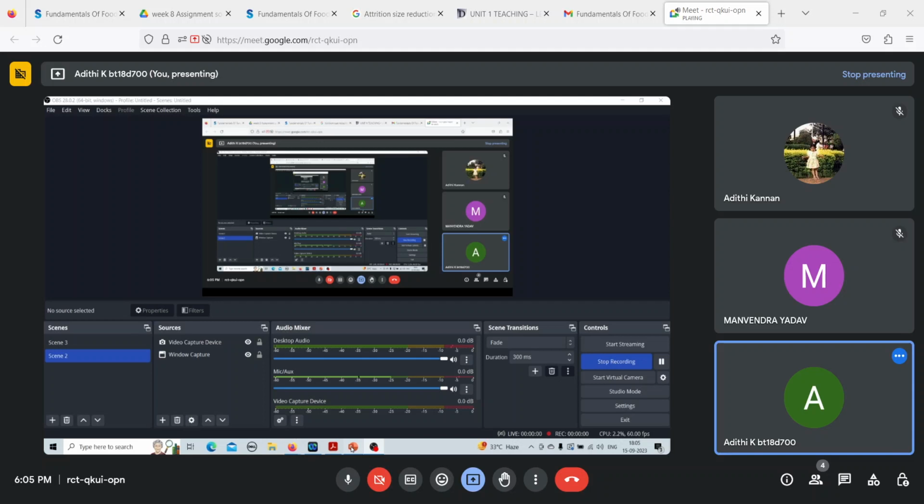Now for the first case scenario, we have XF, we have XP, we have the corresponding energy as well. But we do not know what the Kick's law constant is. So we can calculate it by substituting the parameters for the first case scenario. 8 kilowatts is equal to kk into ln of 15 divided by 2.5, XF by XP. From this, we can calculate the Kick's law constant as 4.46 kilowatt.